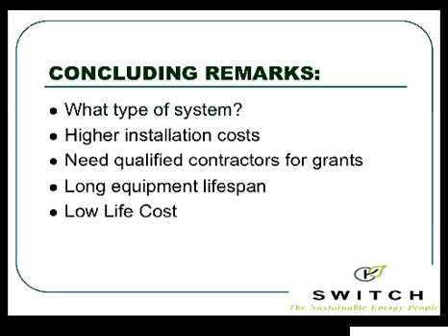What is the supply temperature? The supply air temperature off of it is going to be more in the neighborhood of 85 degrees Fahrenheit, whereas that gas furnace is like 110 degrees coming out of the register. So with your existing ducting, with much higher airflow, this would feel pretty cold. Yeah, that's what I say. It's a higher airflow, and it's cooler. Unfortunately, it's cooler than your body temperature, so it feels cool going past you, right? So it's still heating the house because you're only wanting your house at 70, 75 degrees Fahrenheit, right?